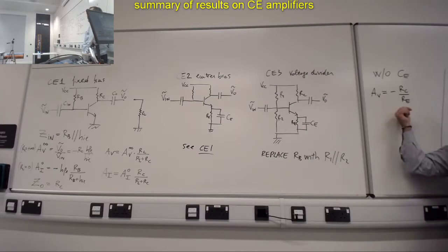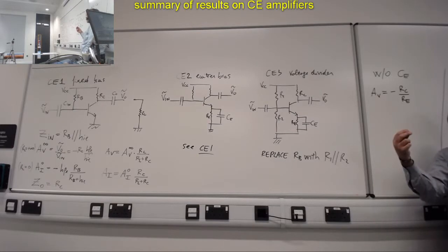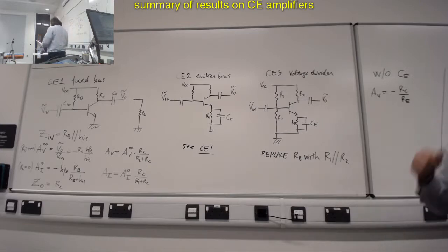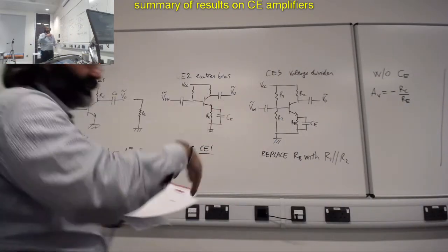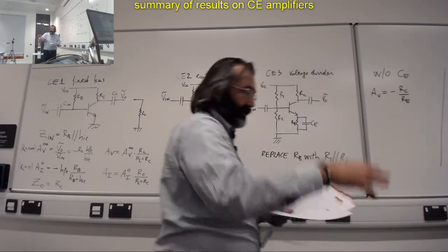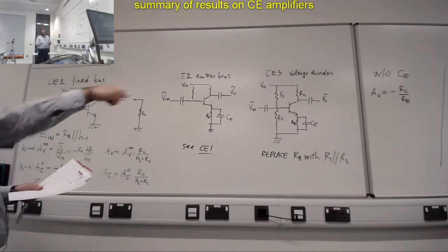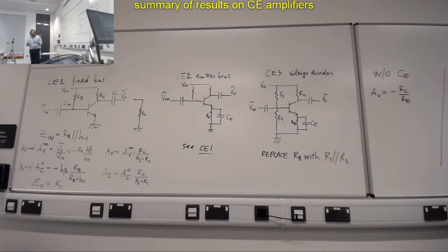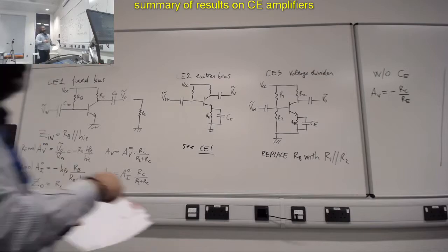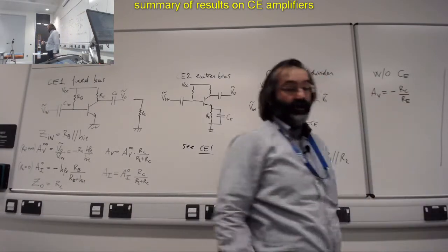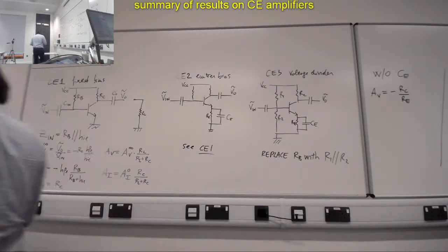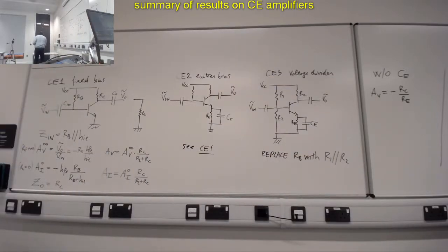So the voltage amplification here is completely independent from the characteristic of the transistor. I've got some circuit applications in the end around these things. So we will come back to this; remember, this is called RE unbypassed, with emitter resistance unbypassed.